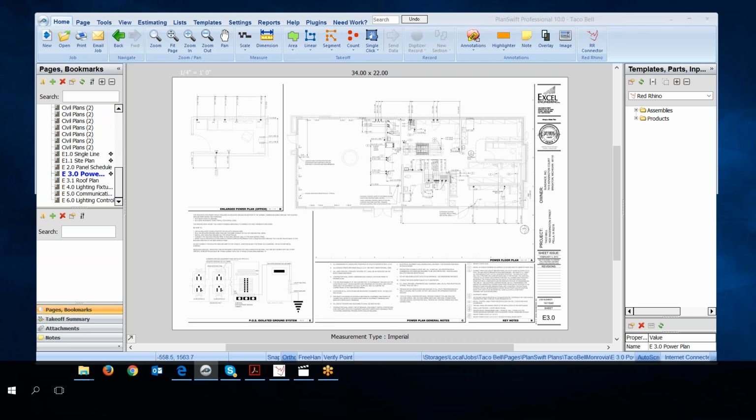I usually go in and spend even 30 minutes or more just reviewing the plans, reading the notes, looking over the blueprints, looking over the specifications to figure out what it is I have to estimate here, okay? So take time to study the plans before you get in there and just start on it, okay? After you do the initial setup, just take time and peruse the plans. Look through all the different pages of it, look at details. Again, get your mind around the project, okay?